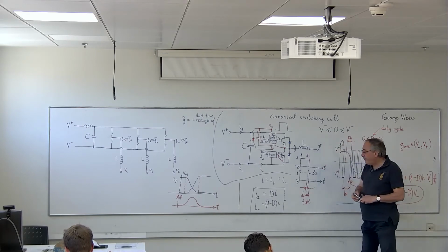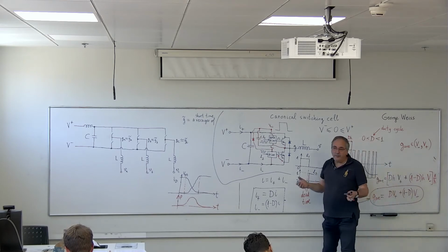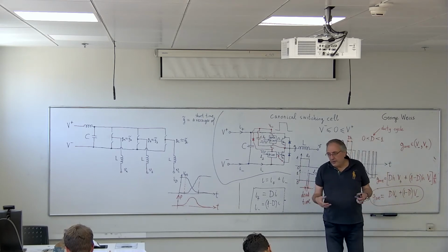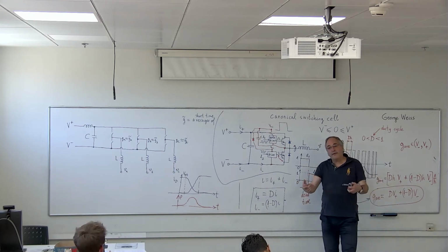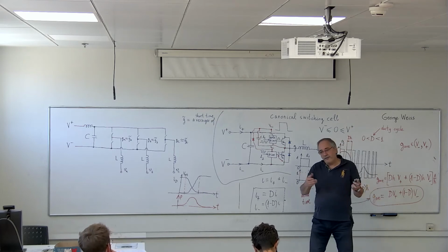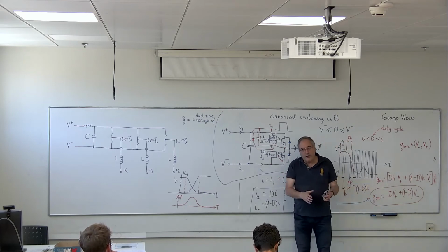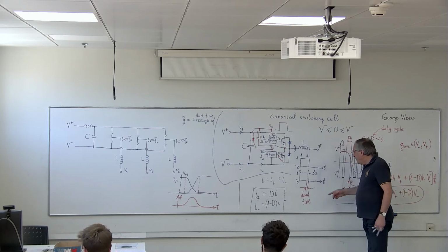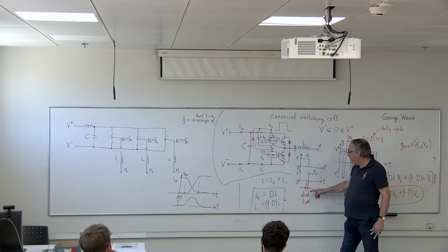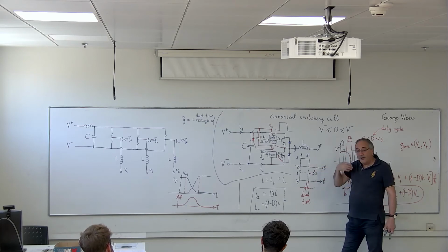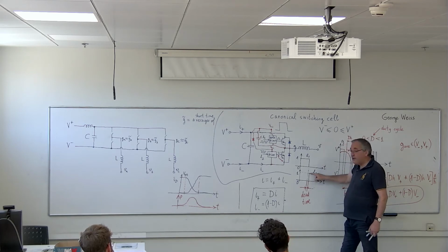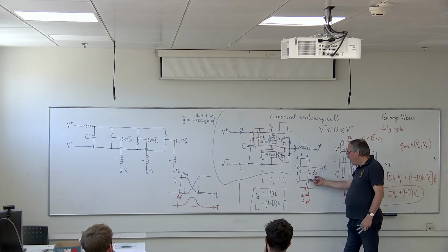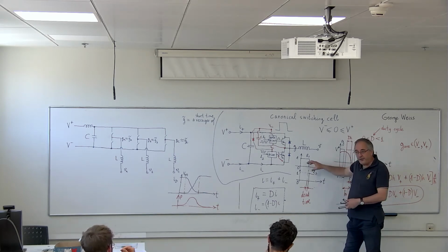So this is meant so that you make sure this dead time can be, let's say, 100 nanoseconds. It depends on how fast the switches are. If the switches are very fast, you can make the dead time smaller. So you see, this dead time is here so that the upper switch stops conducting, and you have to give it enough time to stop conducting before you start conducting with the lower switch. Yes, of course, you do the same dead time also in the opposite direction.